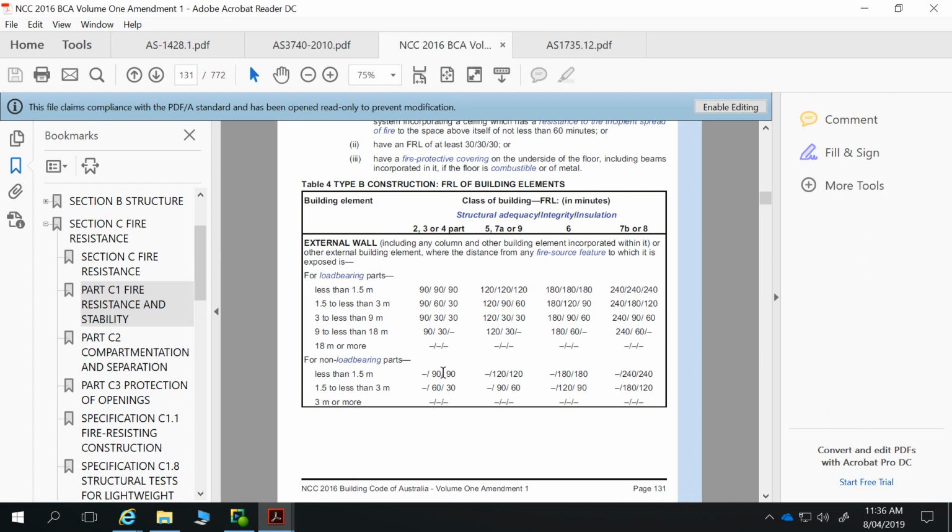But that's an important point in terms of the installation of any fireproof walls, is that they all have to be thoroughly sealed with fireproof mastics to achieve that. But yes, because we don't have to meet that structural integrity, it's going to be dash 90-90 for our separating walls. But for our floors that separate us from a car park, for example, that is going to have to be structural.